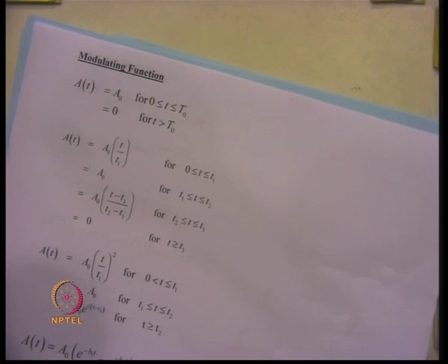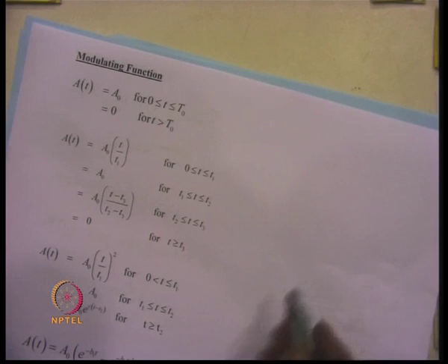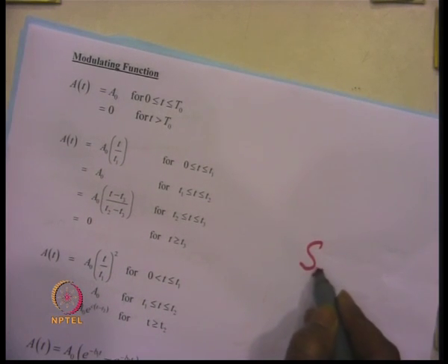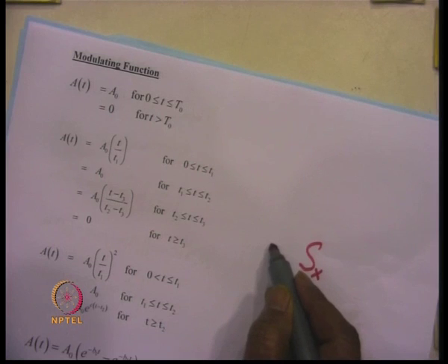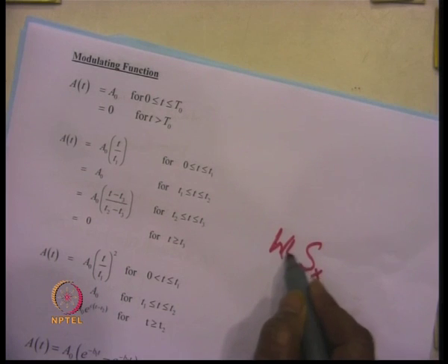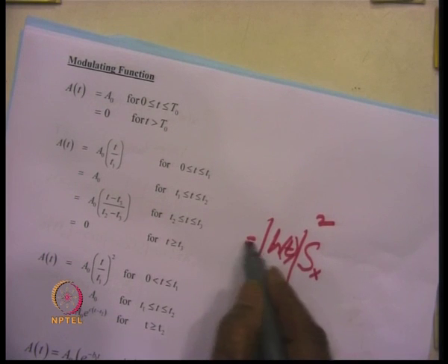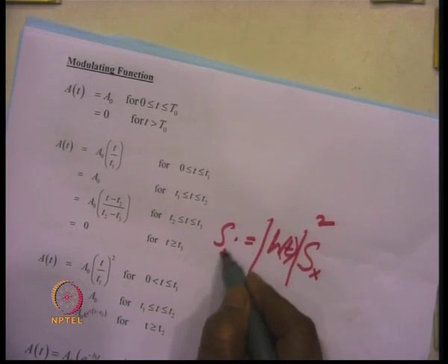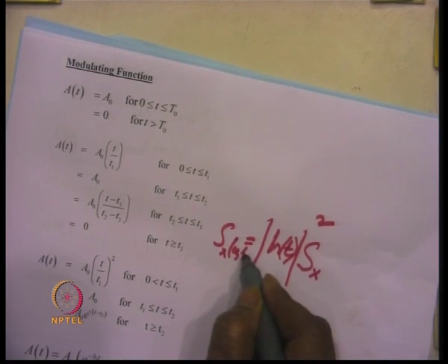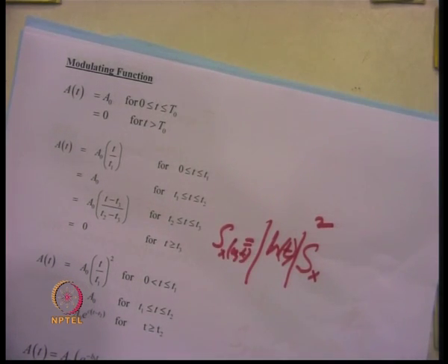And there we had seen that the power spectral density function of the earthquake is multiplied by a modulating function h(t) square, and this gives the value of the power spectral density function as a function of omega and t both. So, various forms of the modulating function were observed from the recorded data.